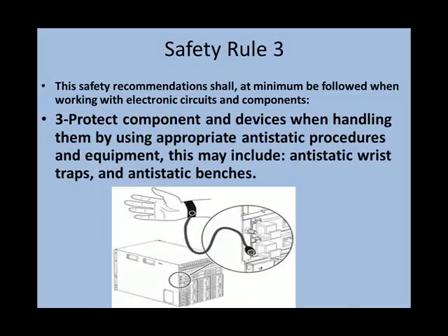Number 3, protect components and devices, because now we're dealing with components and devices that are sensitive to static voltages. And so you need to use anti-static wrist straps and or anti-static benches. Here's the case where the static energy in your body will be discharged onto the frame of the chassis of the bench and not onto the actual equipment you're working on. So always protect those components and devices by handling properly using anti-static equipment.